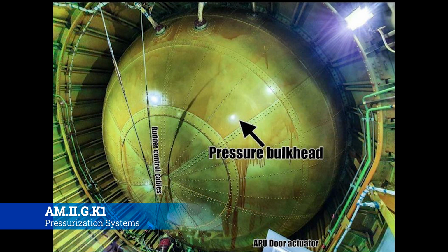So just know that whenever you're working on the pressure bulkhead, or on the exterior of the aircraft, like windows, installing antennas or anything like that, this is something that you need to take into account and have the proper engineering approved data to work off of, because this is no joke. Could be a bad deal if you get it wrong.